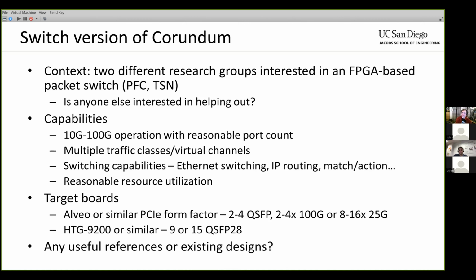But the other one is all of the PTP CDC logic to transfer the PTP clock into all the MAC clock domains. With Corundum, if we only have 2 MACs or whatever, it's not really a big deal if that module takes up a bit of space. But if we're putting 16 or 32 MACs on there, I did some work I talked about last time to reduce the size of the MAC by improving some of the CRC computation. That's all well and good, but the PTP CDC logic is a lot bigger than that.